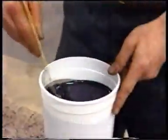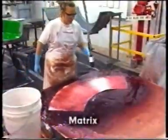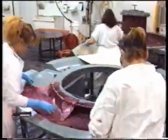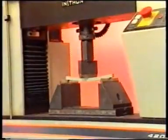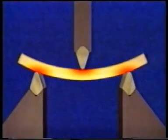Let's review the material contained in this videotape. Composites are made up of at least two distinct intended materials: a matrix or base material and a reinforcement material. The matrix functions as a binder for the reinforcement and controls the physical shape and dimensions of the part. The primary purpose of the matrix is to transfer the load or stress applied to the composite to the reinforcement. The matrix also protects the reinforcement from adverse environmental effects.